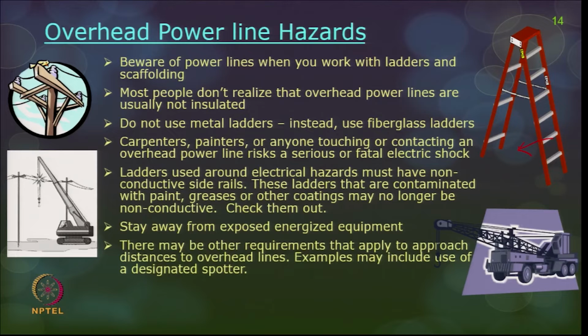Instead, use fiberglass ladders. Carpenters, painters or anyone touching or contacting an overhead power line risks a serious or fatal electrical shock. So, when your construction work progresses up the height, okay, when you are moving up maybe a few stories above, then you should be very careful that you may be venturing into these electrical hazards.